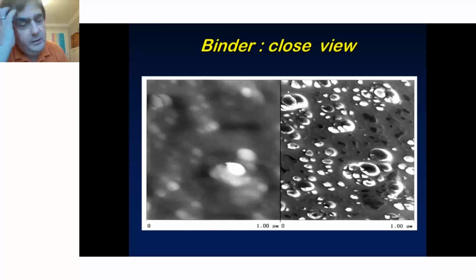So in terms of surface area, you can see there's a few little things stood up out of the surface, but by and large, there's not a great deal of detail there. Over here in the phase system, what we see are these small regions of material, and these regions which seem to be quite dark. Now, when we study this in a bit more detail, these regions here are hard regions, and these black regions between them are the relatively soft regions.